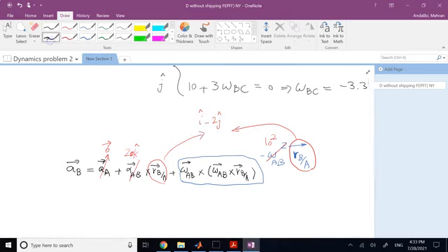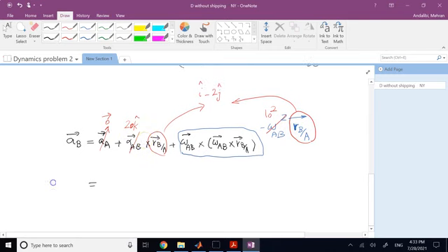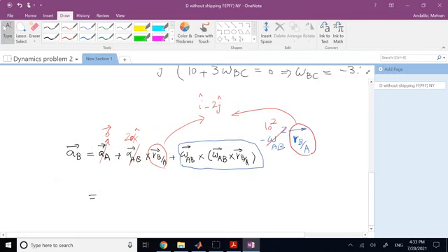So if we carry out the scalar times vector and add it to here, and carry out also this cross product of alpha cross R, so you have a K cross I, which is J, have a K cross J, which is negative I, but there is another negative, so you get positive I. And then you have also a scalar times I and J. So you have two I's and two J's in the total that you have to add together.